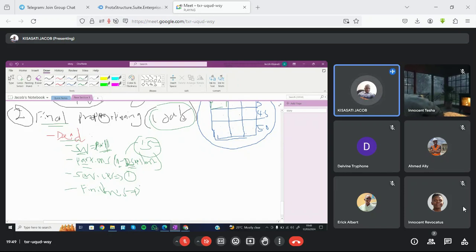Number one, there are things like ceiling board, tiles, paints, curtains, windows. All those things are included. Coming to the kitchen, for example, there are the kitchen cabinets. So all these are what we call the finishes to our building. So how do we calculate the loads for the finishes? It's so difficult to calculate these loads. So what we always do, you assume. So for this one, we always assume 1 kilonewton per meter squared. And it also depends on the nature of the structure.